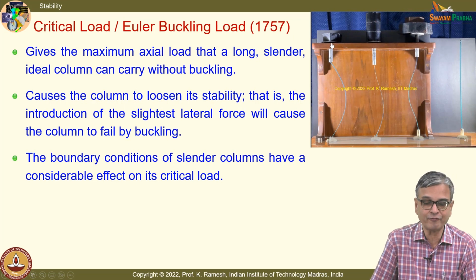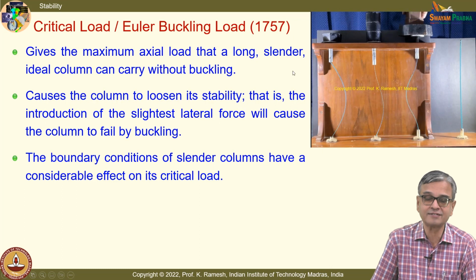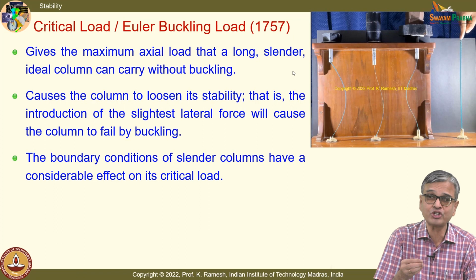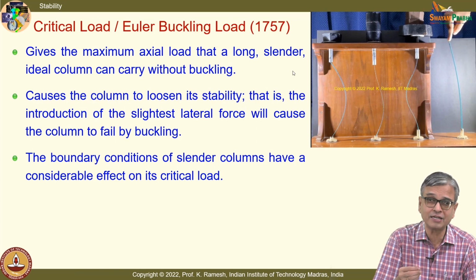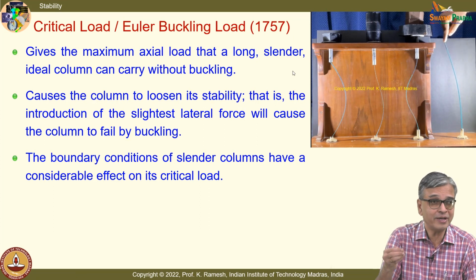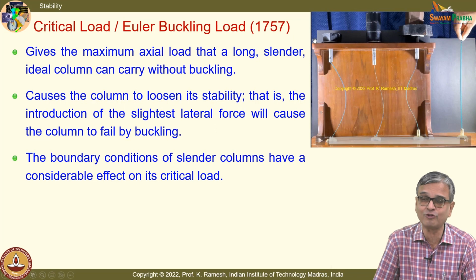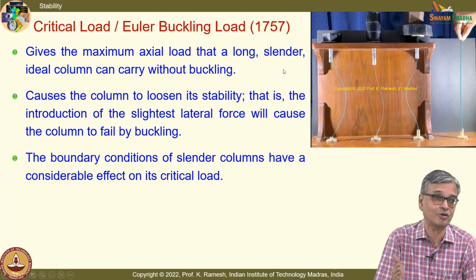If I have to perform the experiment in an idealistic manner to get the critical load, I should have provision to vary the load continuously. The loading system I have shown is not all right, because I have discrete loads. These discrete loads may miss the critical load.